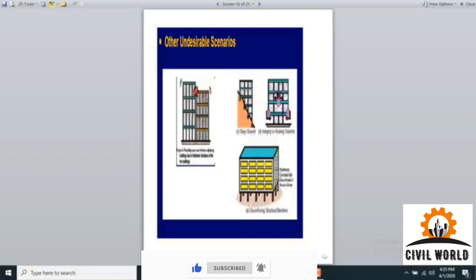In this structure we can see the movement of the structure at the free ends, which are actually the cantilever parts. So when you are having a structure and it is having cantilevers, these cantilevers can be critical at the time of earthquake, and you can have the failure right at these cantilever points.